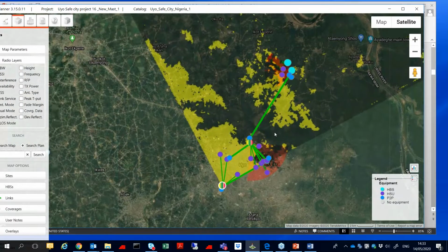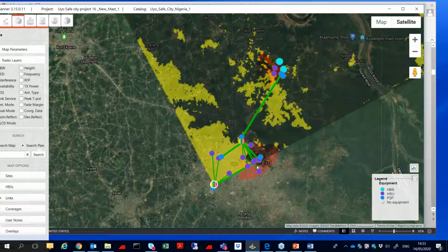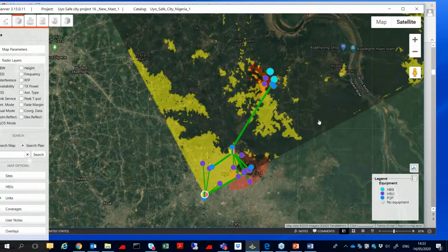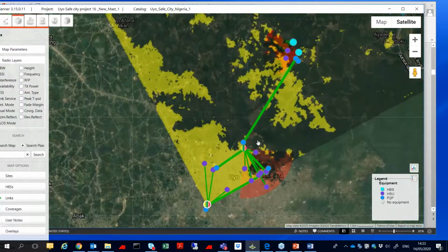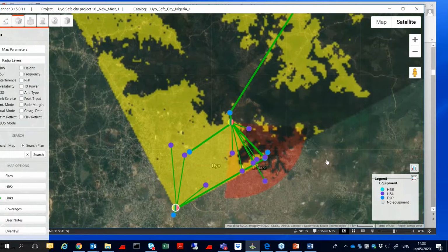Now, so the dark areas are non-line of sight. I don't see buildings. I need to do a site survey. And the coverage area needs to be carefully examined according to calculation of capacity, throughput, density of subscribers, and so on. What is the throughput they want to achieve, and the antenna gain. I know customers that are using the 16 dBi up to 5 kilometers.